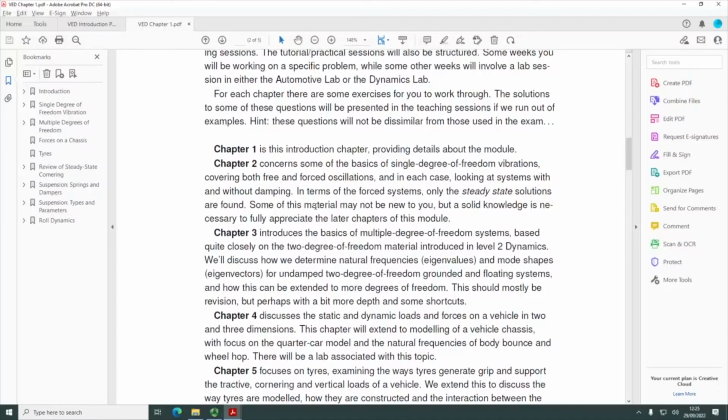Okay, and obviously that middle mass, the tyre, includes the tyre, the hub, the wheel, the brakes and various other things that are part of that unsprung mass. That's what the unsprung mass is. And then between that mass, you've got the vehicle body, or a quarter of the vehicle body on top of it. And there's a typical 2 degree of freedom system.